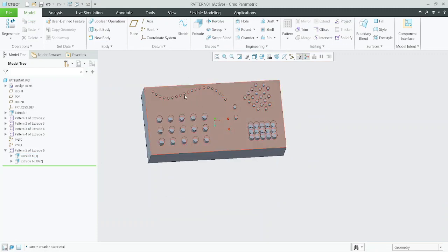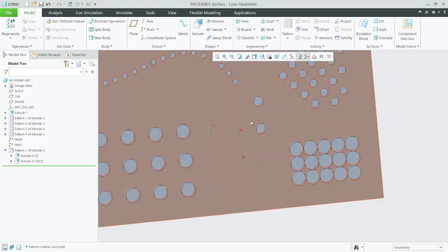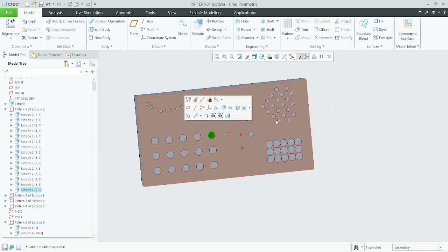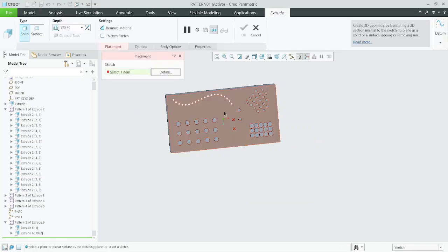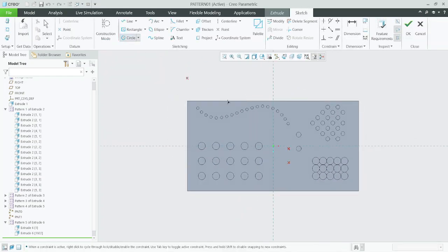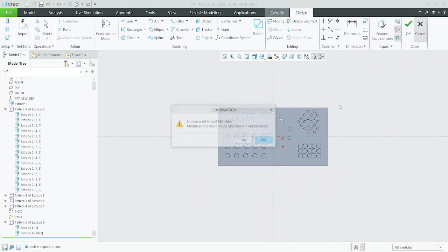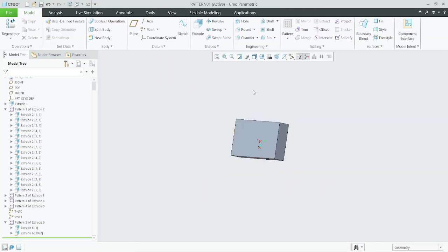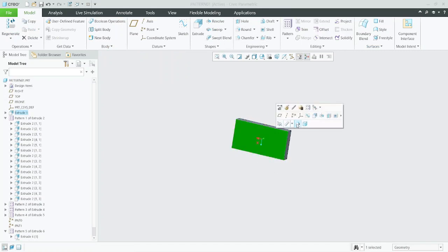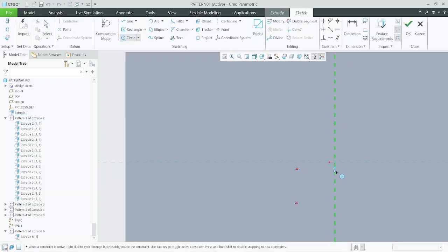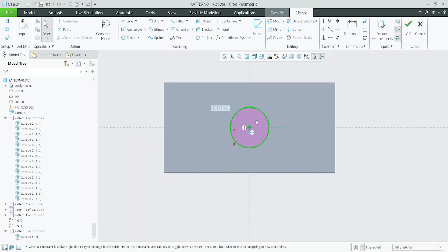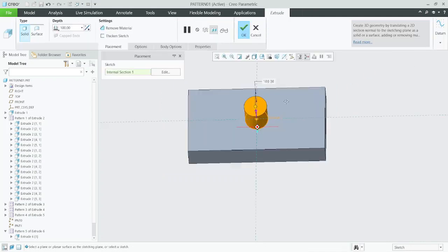And what I will do, extrude on the sketch, or on the backside I will create one cylinder. Go to normal, extrude, I will create one circle, okay, and I will add one datum point at the center of the circle. For this one I will provide 100.